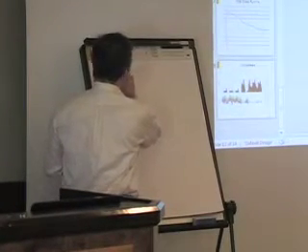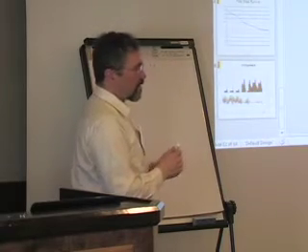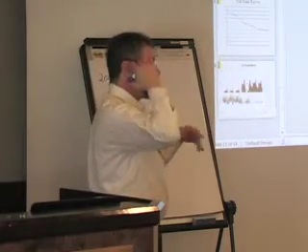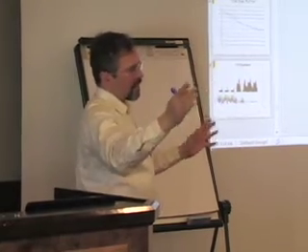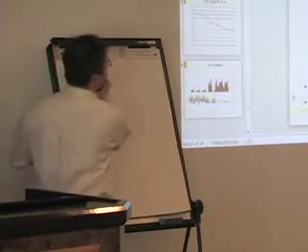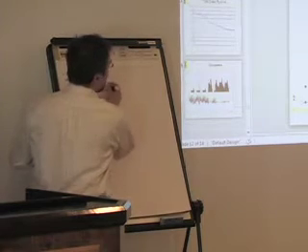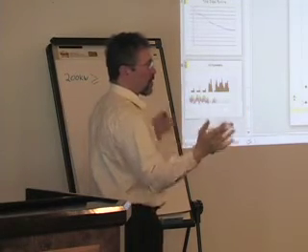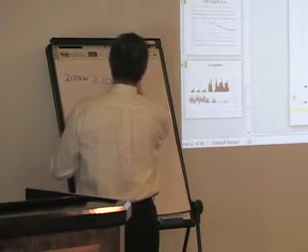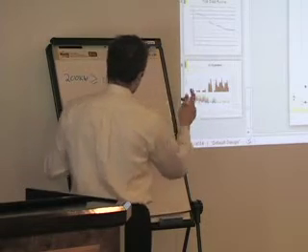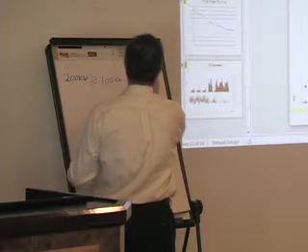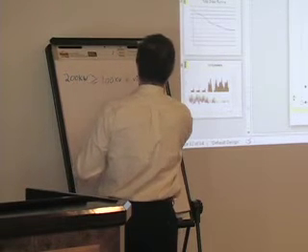So the nameplate capacity of the wind doesn't enter into this at all. But in this case, it sort of does because you're saying it's operating at its maximum. Right? It's a hybrid. It's operating at its rated capacity. So in that sense, it does enter into it. So we're saying 200 kW is the operating capacity. We're saying that has to be greater than the primary load, which is 100 kW, plus X percent of, in this case, 200.